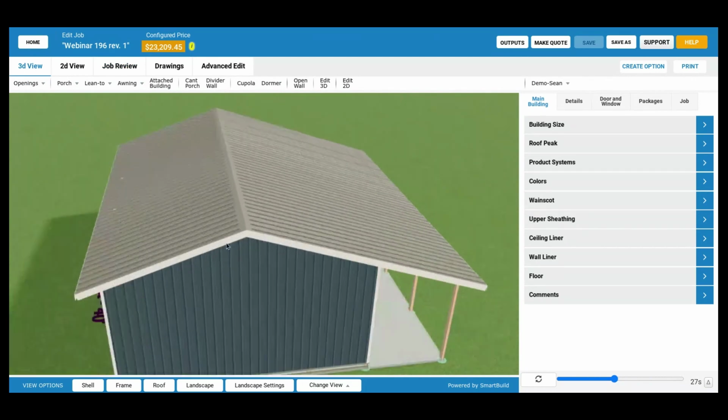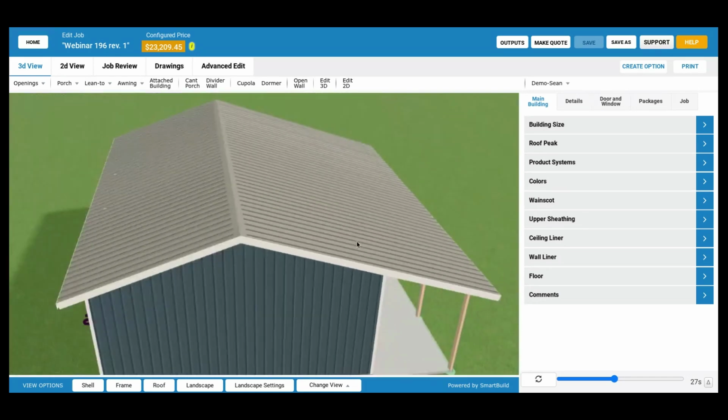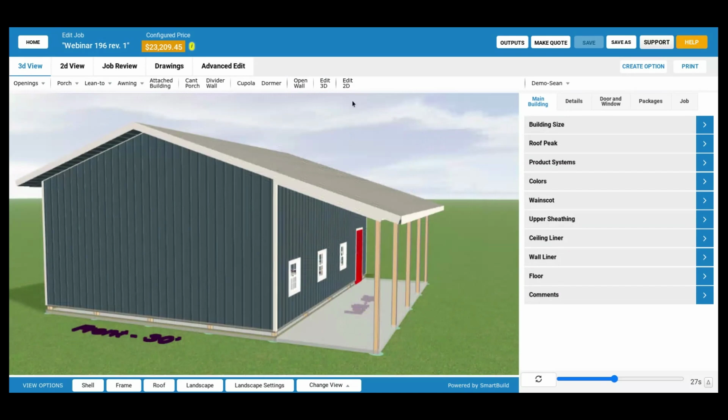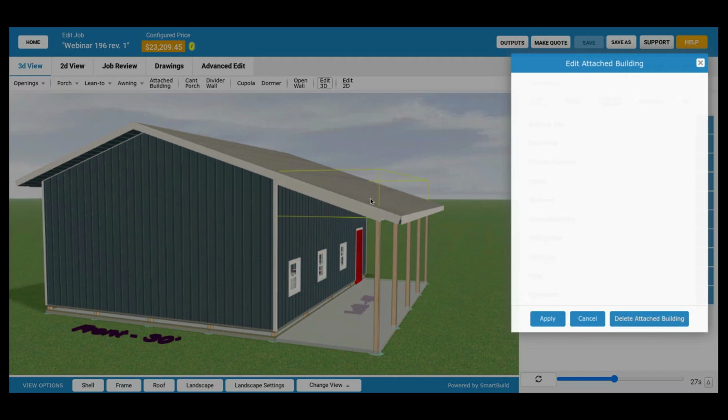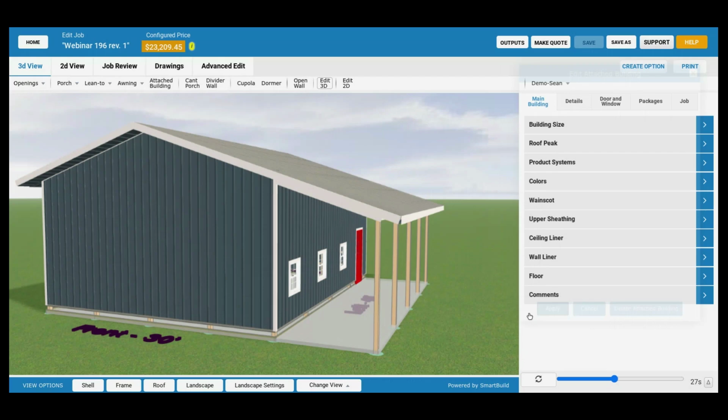Versus if you're running a shed roof, you want it to run all the way out, and half an inch short of the end on the low end and a half an inch short of the end on the high end. And I think what it's asking for there is basically the ability to just say, look, I want the trim to affect the length of the sheathing.